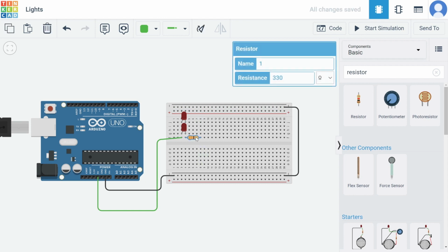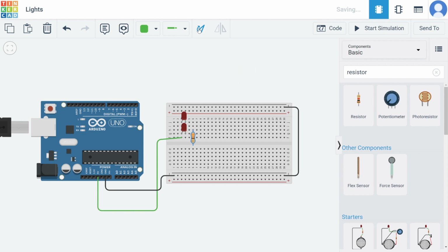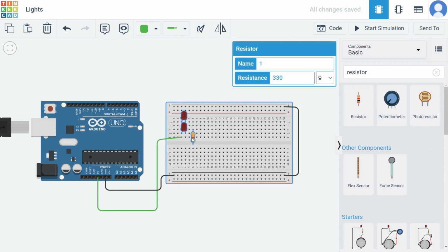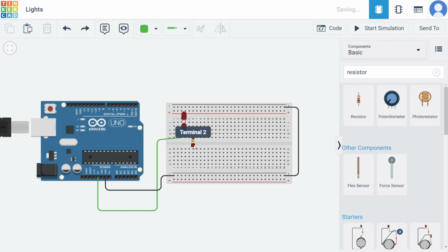Now, if that's the case, I don't want this wire going across here. So what I may actually do is turn this like that. And those 5 are connected, but it doesn't connect to these 5, so I can safely hop over here and then that can go down to ground. And I'll just check that that works for me. Okay, it does.